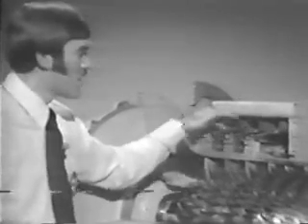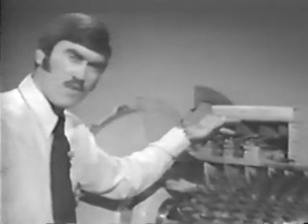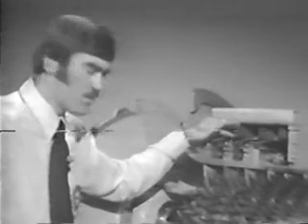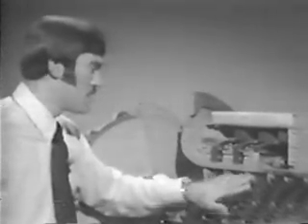The inlet guide vanes and stator assemblies are adjusted automatically with increasing speed during the start cycle to match the forward and rear end of the compressor at all times.